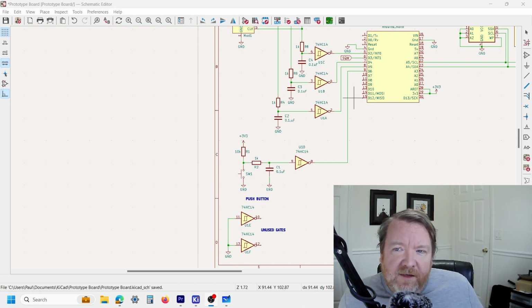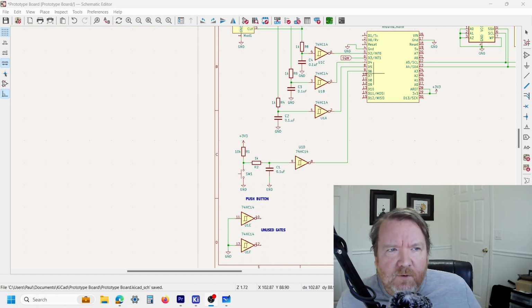If you've got the processing capability in the microcontroller, it might be cheaper to do that programmatically as opposed to electronically. But also, if you're trying to make a very low power microcontroller which has minimal memory or RAM, adding in a software debounce bit of code may cause you to use a more expensive microcontroller.